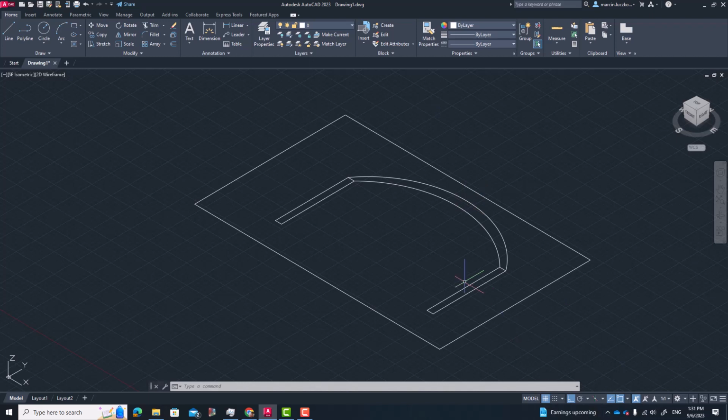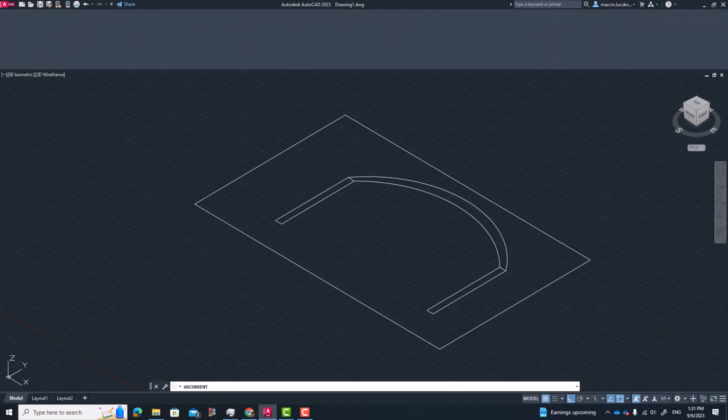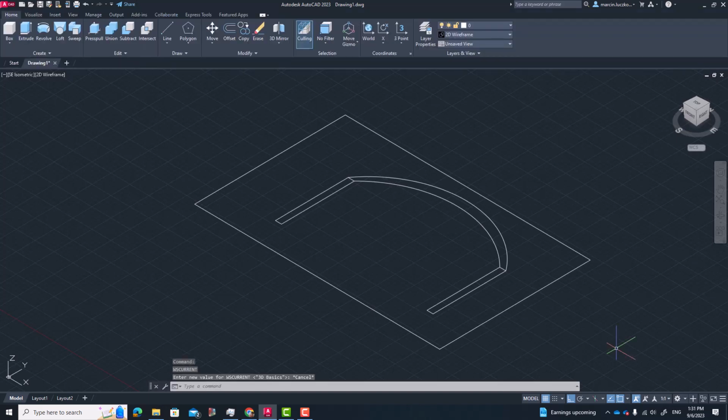Okay, let's go for the generation of the 3D structure. Since those are columns and I would like them to be 20 by 20 centimeters, maybe I can do it with just one box. So I will go here first to change the workspace from drafting to 3D basic. Generally it doesn't change much in AutoCAD. You still have exactly the same commands, but different things appear in the ribbon. So changing a workspace doesn't really affect AutoCAD itself. It only affects the position of the buttons in the software.